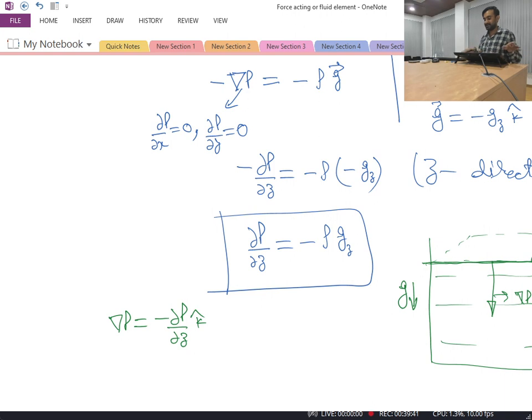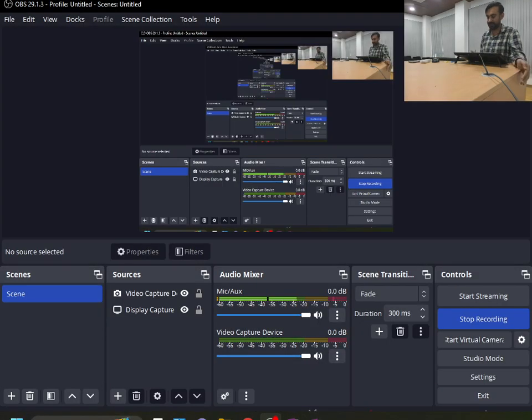If at this entire plane the value of pressure is constant, we will get our free surface at atmospheric pressure, because above this we have atmospheric air. So everywhere over this surface our pressure will be atmospheric, which is a constant pressure. That is the reason that all our free surfaces are horizontal. Now I will stop at this point and we'll have further discussion in the next lecture.